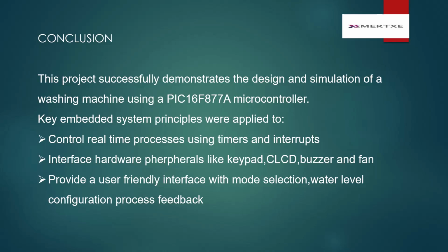This project also demonstrated the design and simulation of a washing machine using a PIC16F877A microcontroller. Key embedded systems principles are applied to control real-time processes with timers and interrupts, and to interface hardware peripherals like the keypad, CLCD, buzzer, and fan. It provides a user-friendly interface with mode selection, water level, and process feedback.